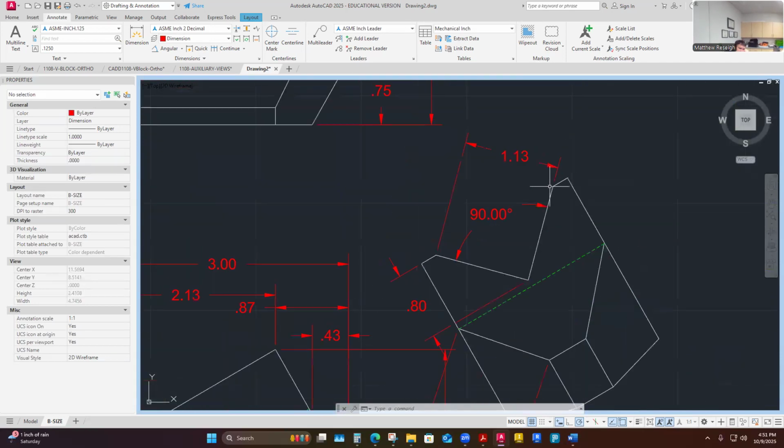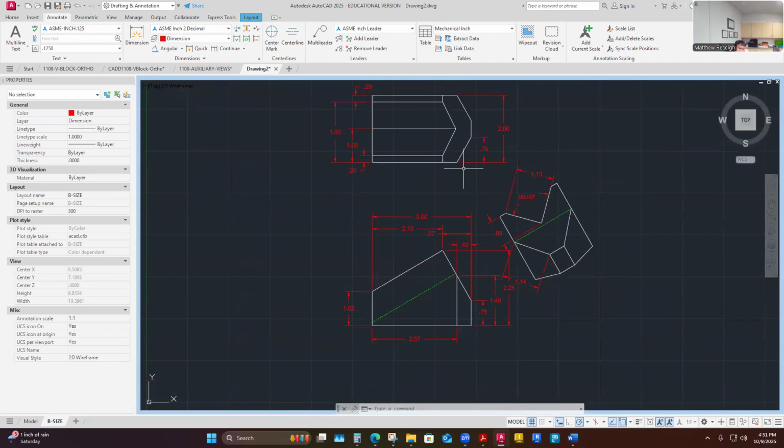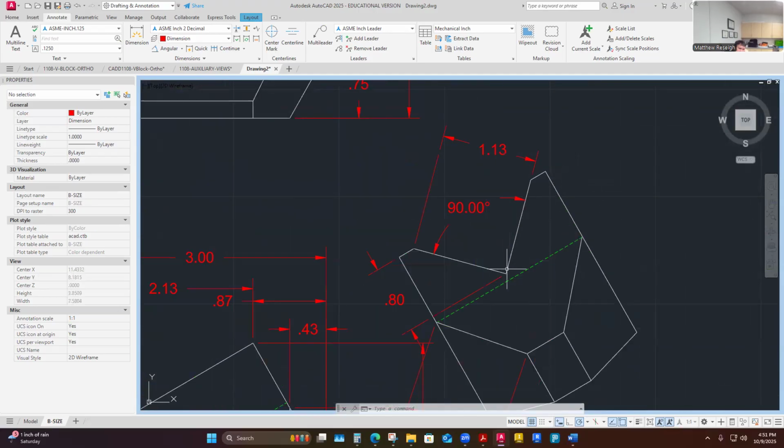It's 0.2 over. Yeah, I've got that over here on the top view already. Okay, and then it comes down. Yeah, there's two of these 1.13s, and maybe that's understood by how I pulled this dimension, or do I need to pull another one or say 2 times? I'm just going to leave this one as a little gray area, but it's 1.13 this way and it's 1.13 this way. And then I go back over 2. So really, I haven't had to add any dimensions yet as I'm analyzing my sides. And I've got a 90-degree potentially reference dimension in the future.